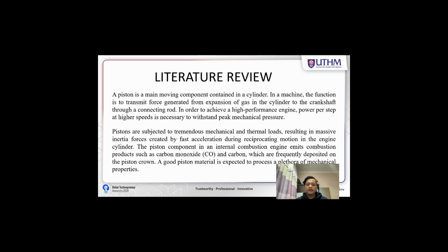In order to achieve a high-performance engine, power per stroke at higher speeds is necessary to withstand peak mechanical pressure. Pistons are subjected to tremendous mechanical and thermal loads, resulting in massive inertial forces created by fast acceleration during reciprocating motion in the engine cylinder. The piston component in an internal combustion engine emits combustion products such as carbon monoxide and carbon, which are frequently deposited on the piston crown. A good piston material is expected to possess a plethora of mechanical properties.